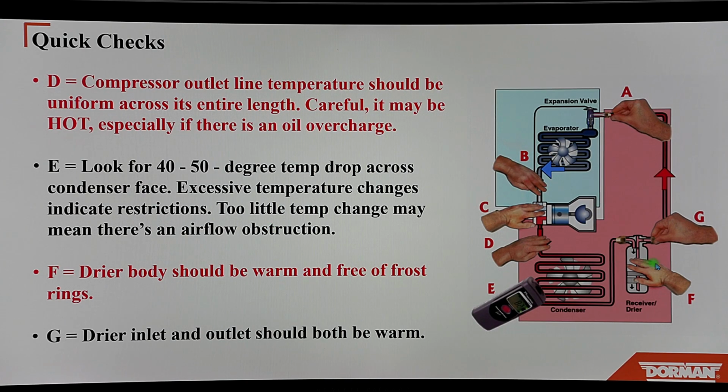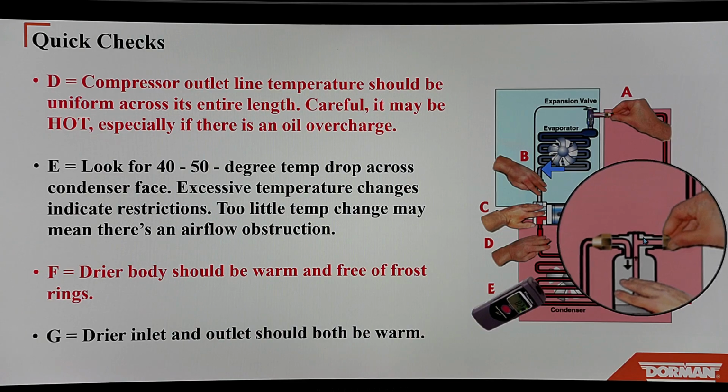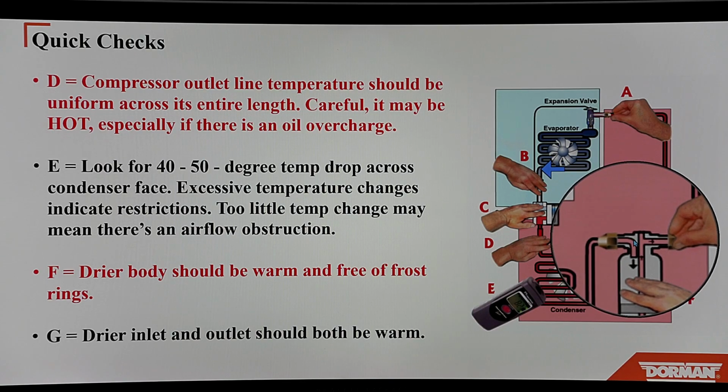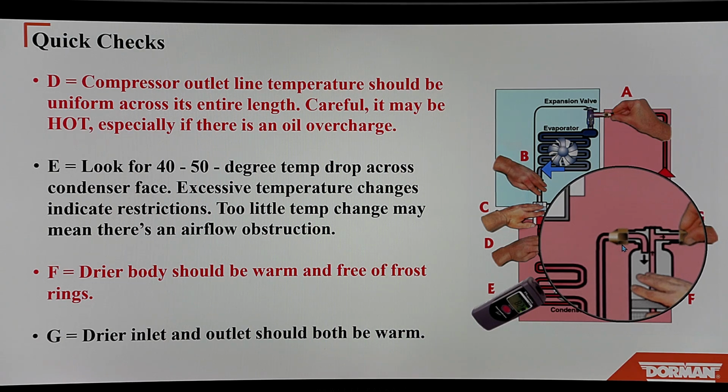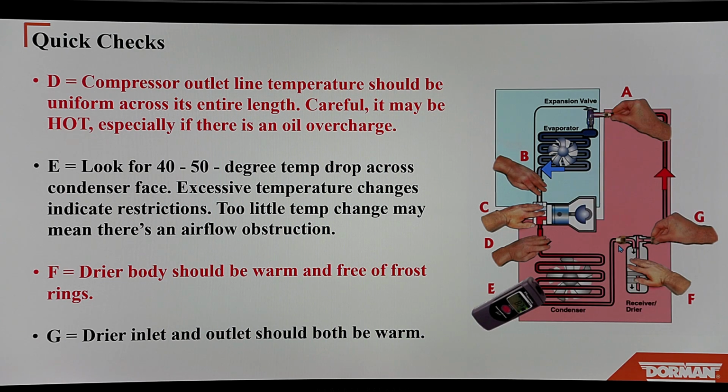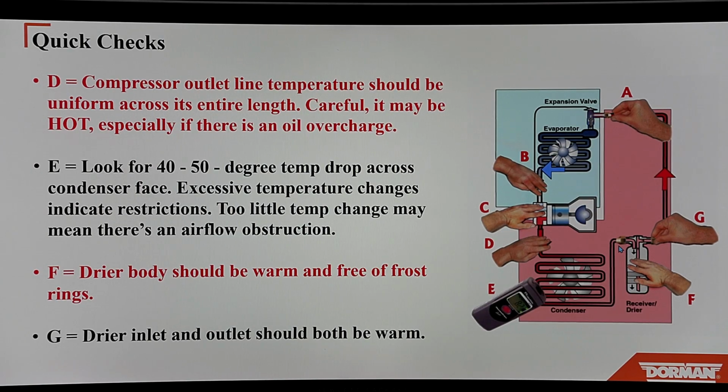F, if you have the receiver dryer, this should be warm and frost free. If you see this freezing up, and by the way, the sight glass, there's a glass on it, they're usually painted. You do not look for bubbles. Bubbles were only utilized in R12. Do not look for bubbles, okay? Only in R12. The dryer inlet should be warm to the touch.